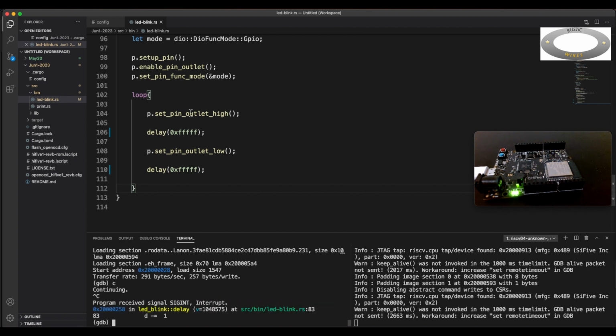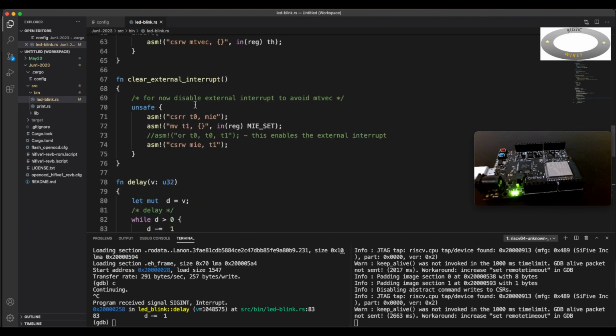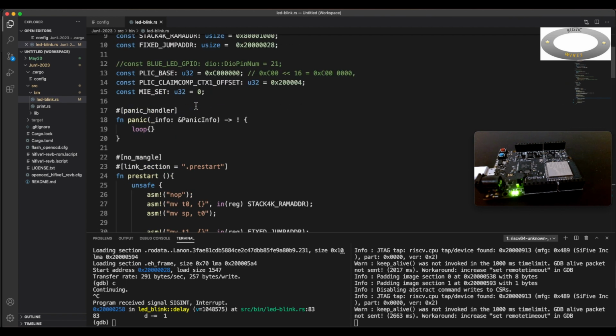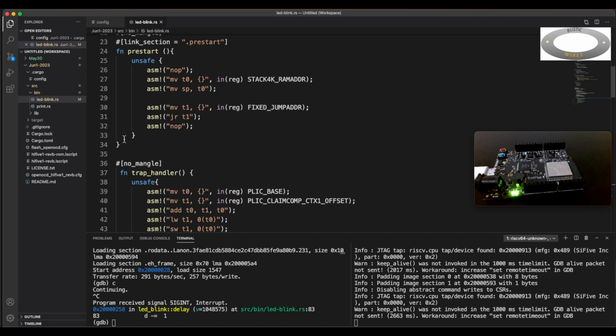So what difference has setting the flash made? Even before, if you connect with GDB and set the stack pointer to some valid address, and then you program, it would work. But what would happen if you just unplug and put the board through a power cycle?